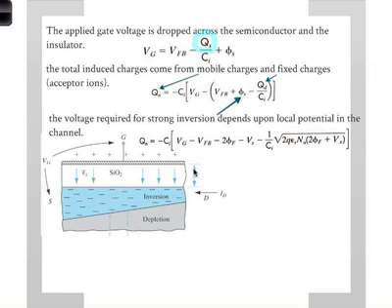It's getting to 0. This is getting more reverse bias, because positive voltage. Remember, it's an N plus P junction. So that is just the depletion charge, which we also derived, I think 2 lectures ago. But essentially, it depends upon the local potential, which is shown here, and the doping concentration.